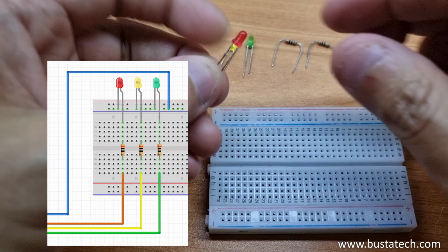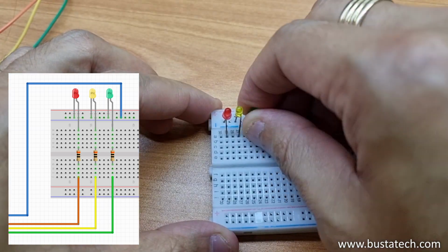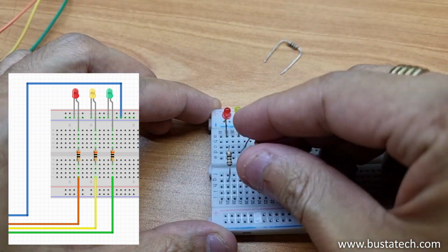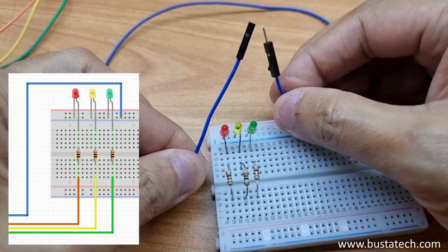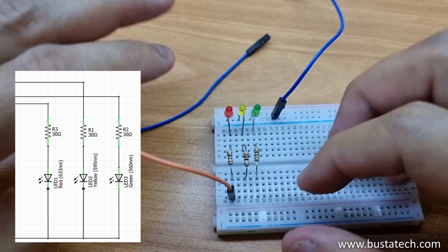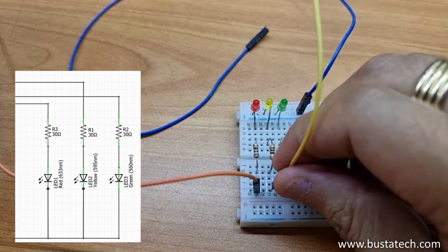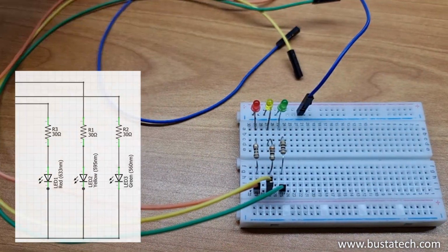Step 2. Prepare your LEDs. Connect your LEDs to the protoboard according to the schematics. Basically, what we do here is add resistors to the LEDs to limit the current through the LEDs. The voltage from the Raspberry Pi output pins is too high for the LED forward voltage. Without the resistor, there is a risk of damaging the LEDs or the output pins on the Raspberry Pi.